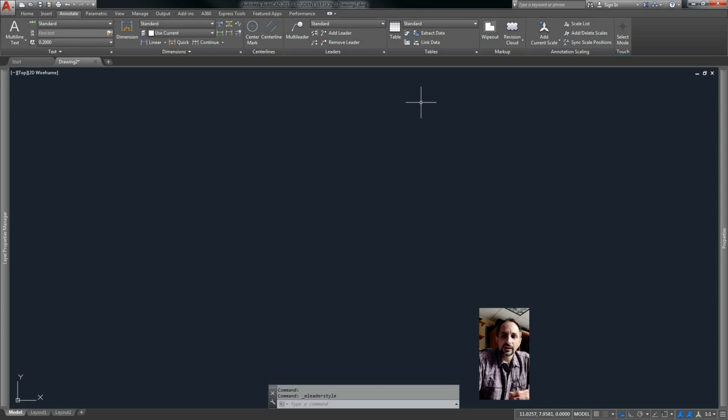Annotative indicates that AutoCAD will automatically adjust the size of the annotative object to match the scale specified. For example, 1/8 inch annotative text will always print out to exactly 1/8 inch height, no matter how large or small you show your model, and regardless of the scale shown in your viewport. Look for the three-sided annotation symbol, which represents that you're using an annotative style.